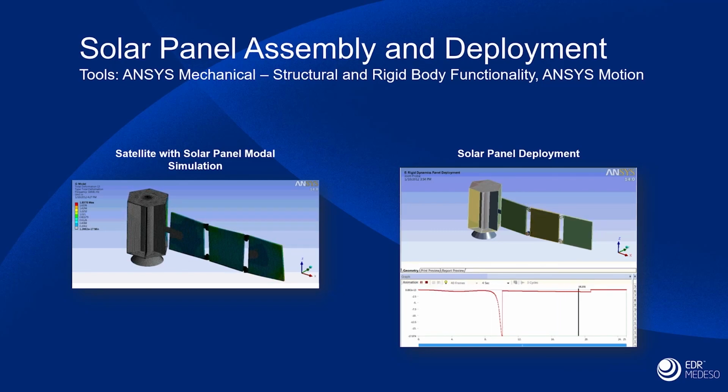We can look at the structural response when we're deploying and assembling these systems. We need to deploy them. In this case, we've got solar panels reliably and with the opening sequences very closely controlled. We don't want things like excessive displacement from attitude control events. We've also got to withstand the thermal cycling within the whole life cycle. And we've got to withstand shock and impact loads during launch. So all of these different loading conditions can be built into our analysis systems, in this case, an Ansys Mechanical environment. And it gives us an understanding of the system modes of behavior.